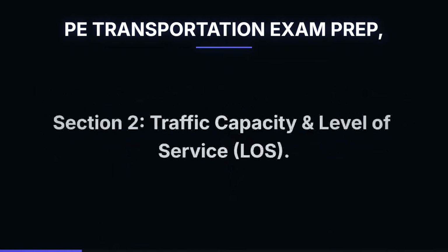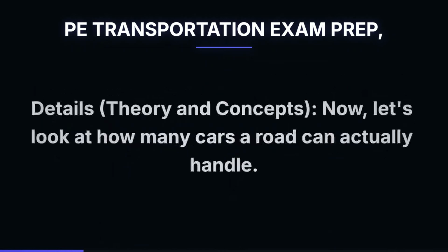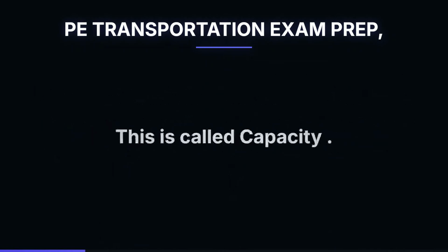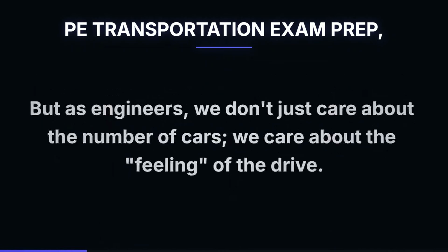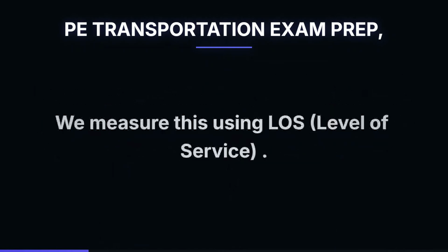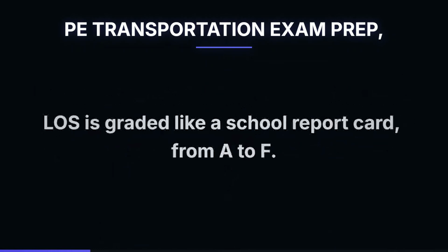Section 2. Traffic Capacity and Level of Service, LOS. Details, theory and concepts. Now, let's look at how many cars a road can actually handle. This is called capacity. But as engineers, we don't just care about the number of cars. We care about the feeling of the drive. We measure this using LOS, level of service. LOS is graded like a school report card, from A to F.